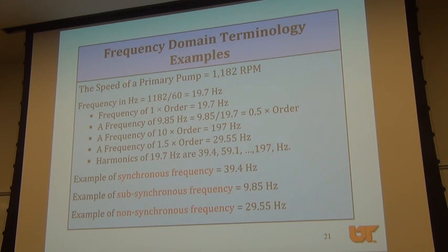So the no load speed of this pump is probably 1200 RPM. As you load the motor, that means as you start the pump, the motor has to do work to pump the water, so the speed of the motor will go down a little bit. Induction motors have the property that they have to slow down, otherwise they can't generate enough power. So the main shaft speed will decrease a little bit.